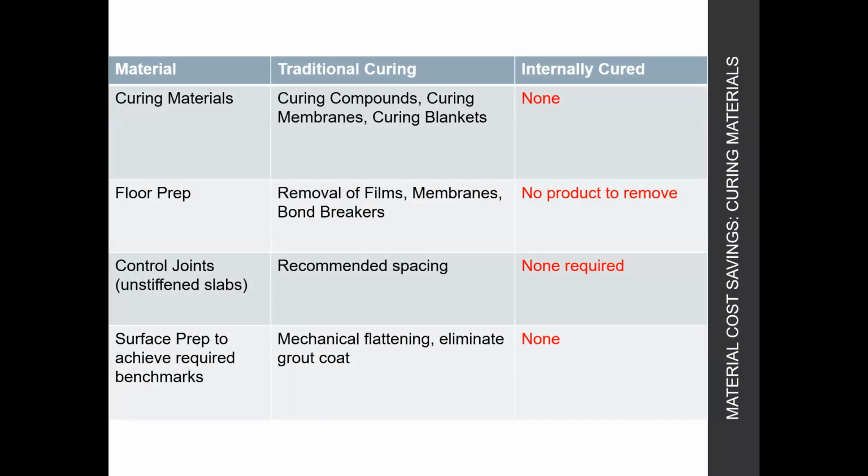I'll jump in here. So you've got control joints happening when they're required. Obviously, the type of slab is going to dictate whether you need them at all. But by maintaining most of the volume, not having it bleed out into the atmosphere as vapor, your movement in the slab is reduced to the point that the need to adjust for some of those changes, as you see with commonly curing or not curing with resinous materials, silicates, things like that, are going to be reduced, if not eliminated. On the operational side as well, this is handy because 60 to 70% of your maintenance and your headaches for facilities, particularly with hard-wheeled traffic, are going to come from constantly needing to repair those joints.